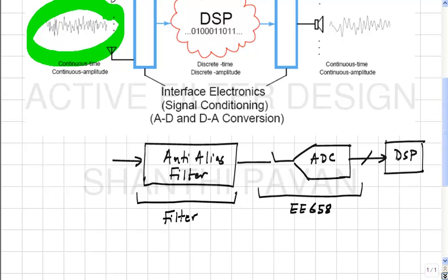And since more and more processing is done digitally these days, it thus follows that whenever you do digital processing, you need an A to D converter. Whenever you need an A to D converter, you need a filter, right? So filters are everywhere in electronic systems and also in daily life. Our eye is an optical filter. It only responds to EM waves in a narrow bandwidth, right? 4000 to 7500 angstroms. The ear is an acoustic filter which responds to, if you're lucky, 20 hertz to 20 kilohertz. Okay. The mouth is also an acoustic filter, right? It doesn't always filter what you want it to, but right.